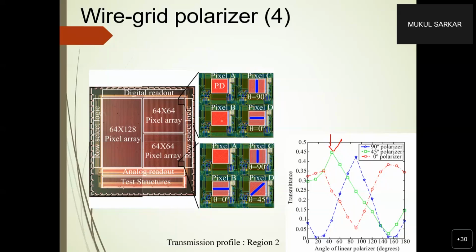Yes. If you work in ROI based readout modes, for example, if you have a 10 megapixel sensor, you might not need 10 megapixels every time, right? If you need just 1 megapixel, you use a 1 megapixel ROI and read it, because you're not activating the other 9 megapixels, right? The power consumption will be substantially lower, right?